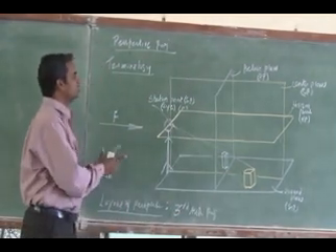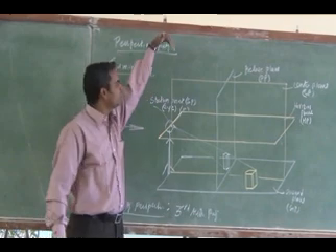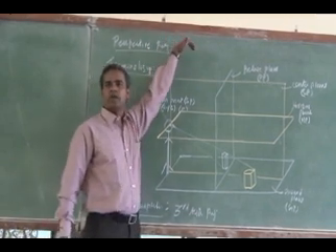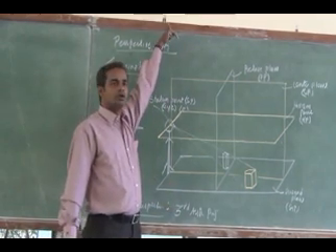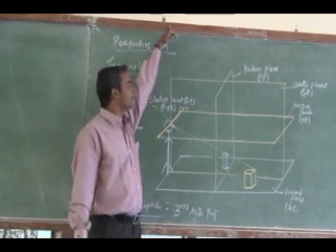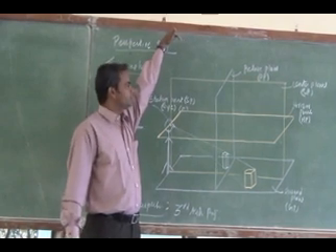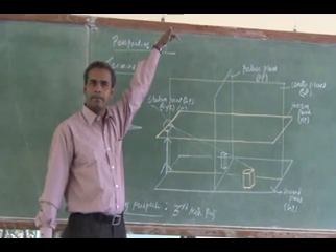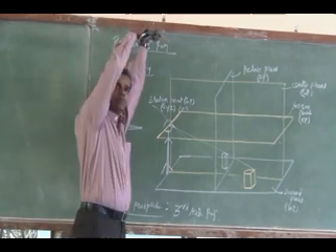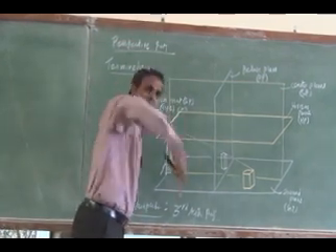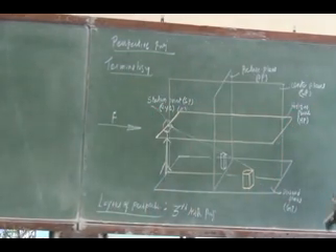So first of all the top view. This is the front direction, the whole setup I have to look at from this one. That is going to be my top. First of all, you tell me, in my top view, which plane will be seen as a horizontal line? Listen carefully, this is the front direction, this is the top direction. Which plane can I see like this? Picture plane. The picture plane will be seen as a horizontal line in my top view.